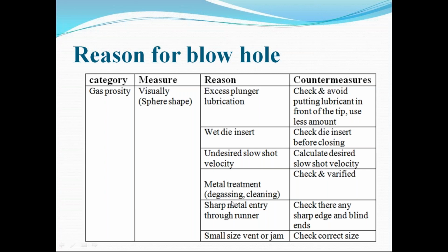Now the next one, this is metal treatment, degassing, cleaning. Before preparation of the metal, that means before filling the cavity, it's required to treat it by degassing or cleaning. If gas or inclusions are available, then gas porosity can develop.